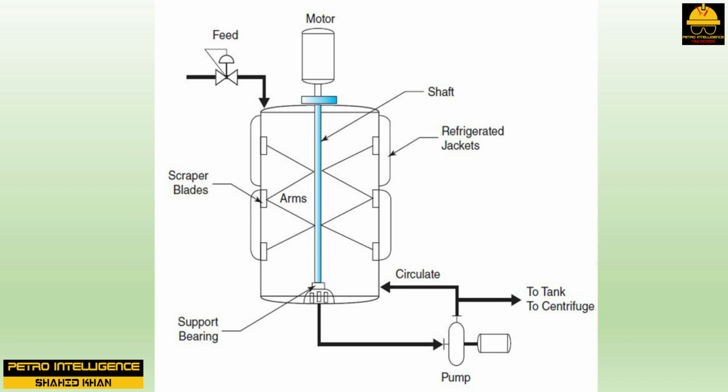As the temperature is lowered in stages, paraxylene freezes. Paraxylene forms crystals that join together, increasing in size as it freezes. Metaxylene and orthoxylene have lower freezing temperatures and remain in a liquid state. The cake of paraxylene on the walls of the crystallizer is scraped off and dropped to the bottom, where it is pumped to a tank. From the tank, it is sent to a series of centrifuges. The centrifuges separate the cake paraxylene from the liquid and send it to a refinery tank.